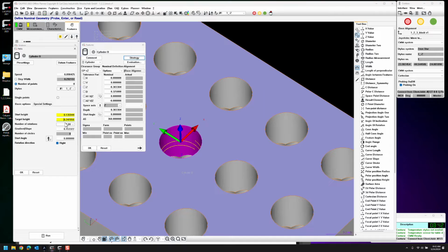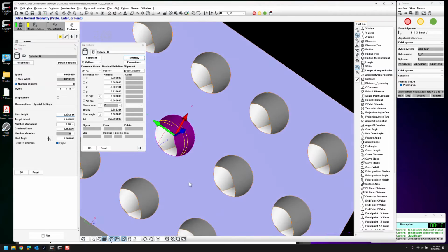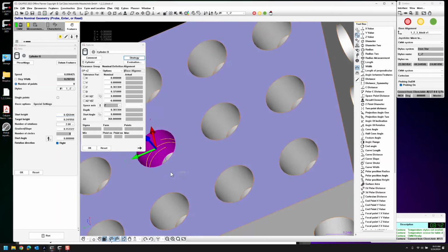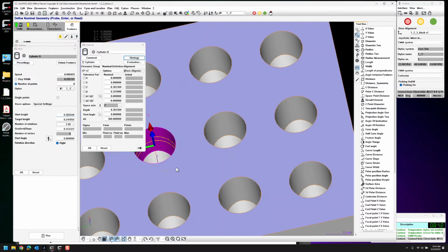And so now we have a higher value. I'm going to go ahead and convert both of these to input fields. I do that just in case somebody runs the program in metric. These will then properly convert. If I leave them as formulas, they'll of course always be inch numbers. And of course we see a very nice 2-rotation helix right there in the middle of our threaded cylinder.